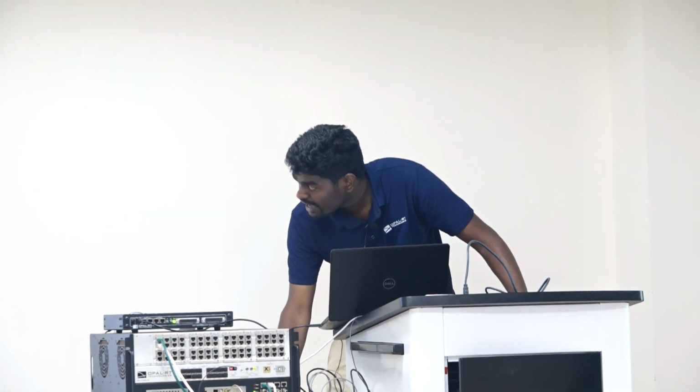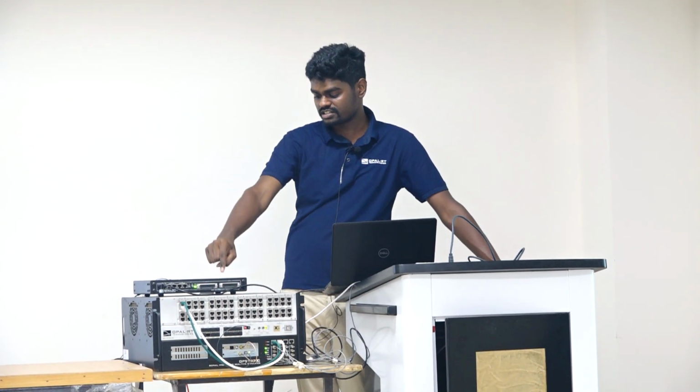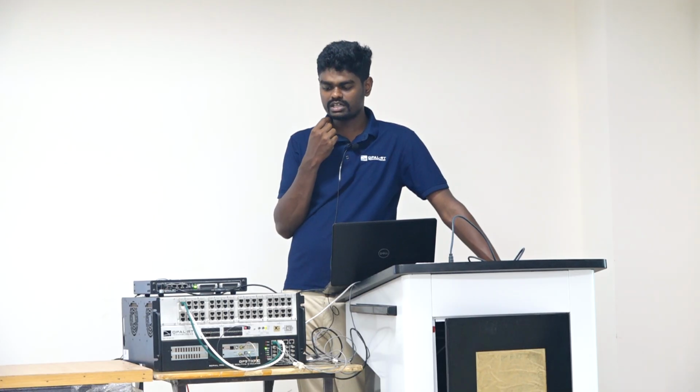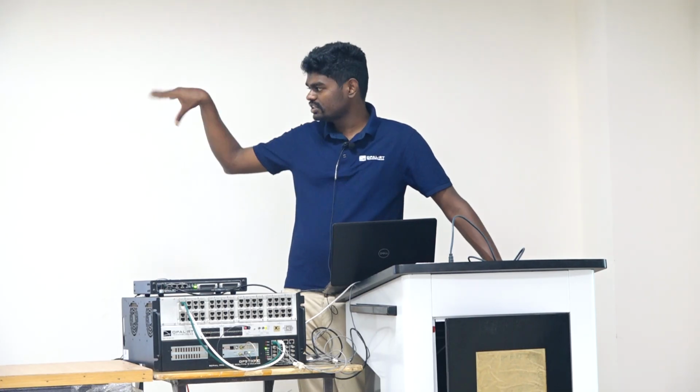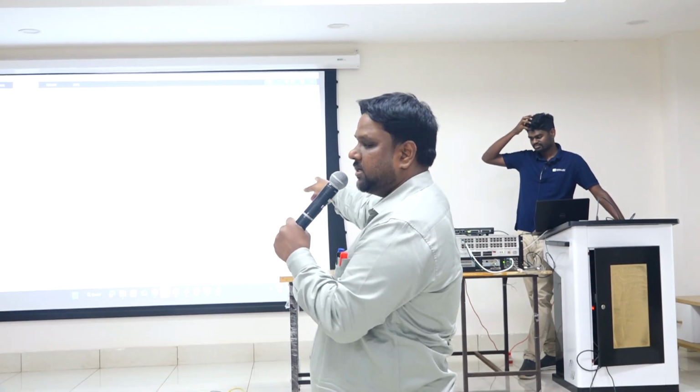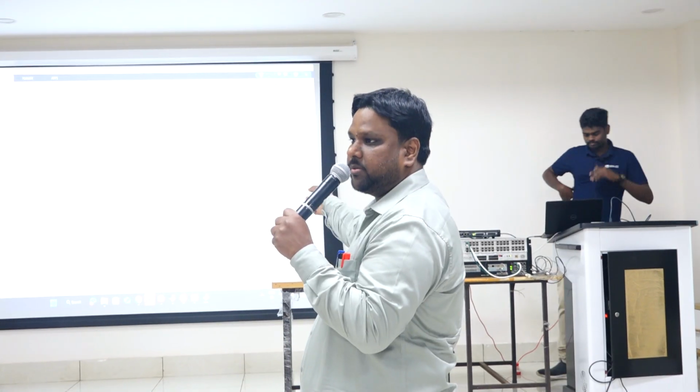The PWM for this inverter is going to come from this controller which is outside. To do that, we first need to send the feedback signals from this simulation model to the external controller. So you need to configure analog outputs on this simulator to send the feedback signals. The inverter is basically a 3-leg, 2-level, 3-phase inverter. There are 6 switches, and we discussed the DC-DC converter. The switch pulses have to come from the controller.